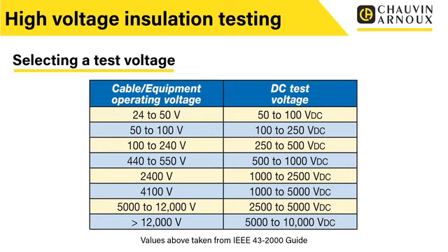So depending on the application that you're working on, depending on the actual type of equipment and its rating, that's where we would look to see what would be a suitable test voltage. So this was taken from an IEEE guide. But again, this is quite common in many standards, and it's always worth looking if you've got equipment that's rated to, certified to a certain standard. Obviously, have a look in that standard to see what test voltage they recommend, and obviously, we'd also recommend consulting the manufacturer.